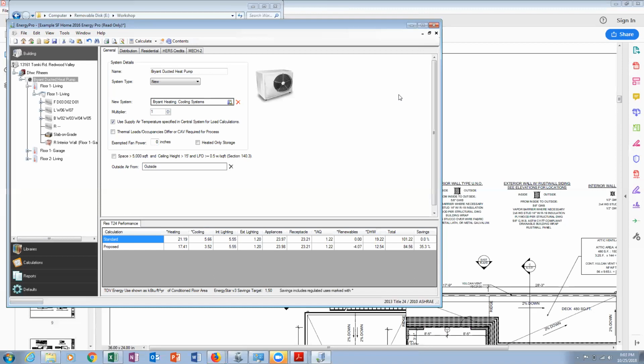is showing that there's like added exterior insulation on a wall or added interior insulation, which is not just the cavity insulation where regular like fiberglass batt would go. It would also show like your continuous rigid foam board insulation or something on the outside. So those are still functional in either software, but you could develop the wall a little bit. You could have more control over it in CBECC-RES.